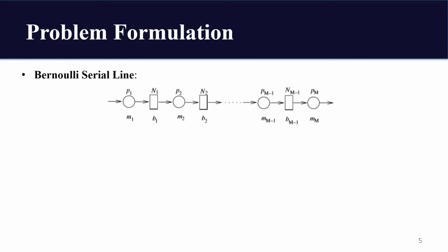This is a multiple machine Bernoulli production line. The circle represents an actual machine, a manual processing workstation, or a mini cell, depending on the nature of the work carried out and the scale of the study. Machines follow the Bernoulli reliability model. Similarly, the rectangle represents the buffering and material handling mechanisms between the machines, which may take various forms on the factory floor.